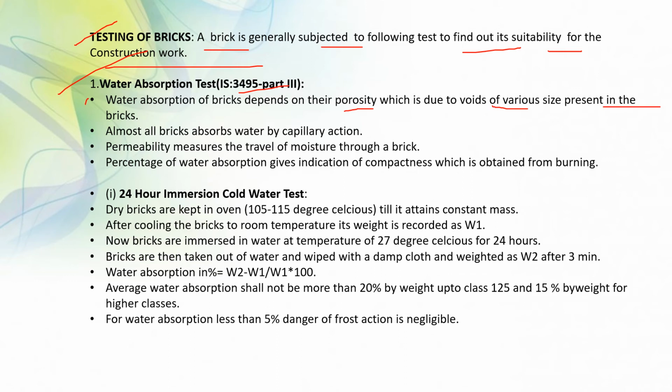present in the bricks. Almost all bricks absorb water by capillary action. Number 2, permeability measures the travel of moisture through a brick. Next, percentage of water absorption gives an indication of compactness, which is obtained from burning. Next, 24 hours immersion cold water test.